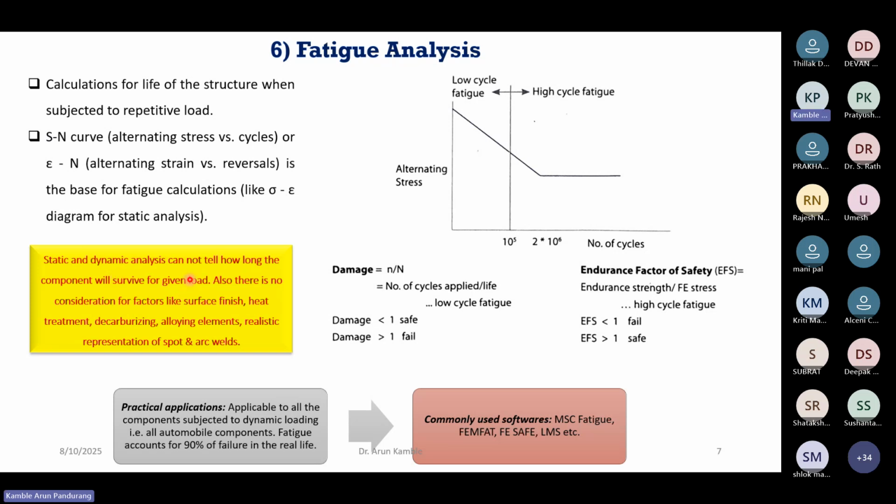Static and dynamic analysis cannot tell us how long the component will survive for the given load, and there is no consideration of factors like surface finish, heat treatment, decarburizing, real alloying elements, or the representation of the spot and arc welds. Therefore, all these factors we consider in the fatigue analysis.